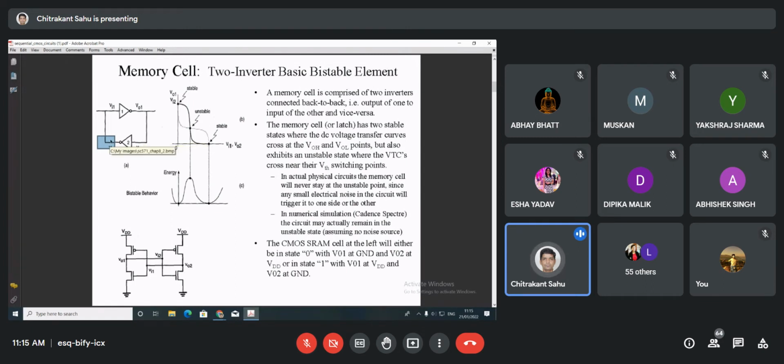And then if it is a low input, now it is going to the next stage. Again it is disturbed, so it may be disturbed at this particular point, right? That will be considered as another point, that is called VIL, input low. So these four parameters decide the noise margin of the device.